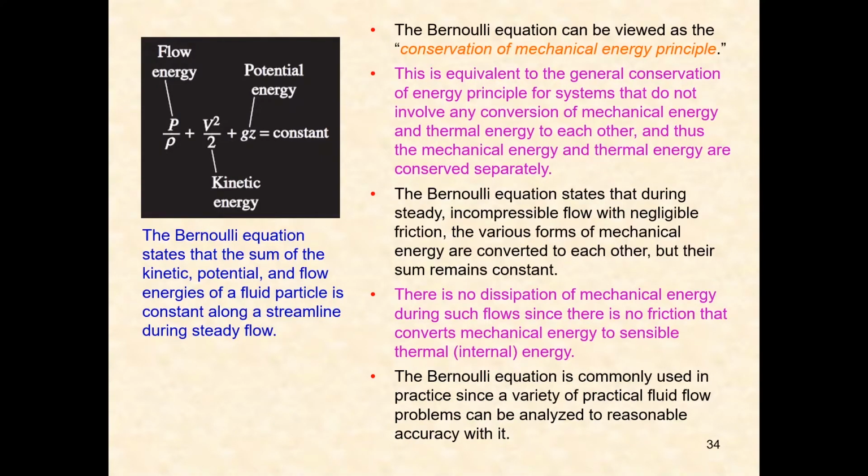The Bernoulli equation can also be viewed as the conservation of mechanical energy principle. The difference compared to the mechanical energy that we learned earlier is that this does not involve any conversion of mechanical energy into thermal energy. So there is no energy loss, and no additional energy supplied into the flow from shaft work, for example, or dissipated from the flow as thermal energy. There is no energy loss in the Bernoulli equation.